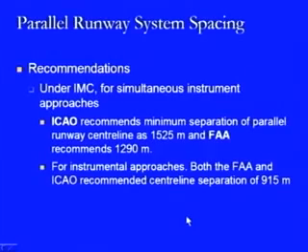Then in the case of IMC, for simultaneous instrument approaches, the ICAO recommends a minimum separation of parallel runway center line as 1525 meters, whereas the FAA recommends this distance as 1290 meters. In the case of instrument approaches, both the FAA and ICAO recommend a center line separation of 915 meters. So, these are certain recommendations as far as the provision of the different parallel runways are concerned.